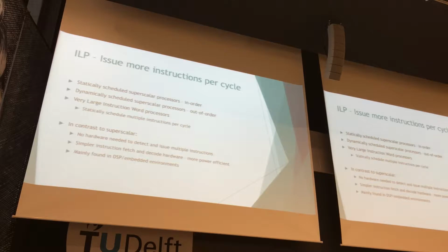Now you basically have, these days, two approaches: a superscalar processor or a VLIW processor. With a VLIW processor, as you already alluded to, it is compiler based, so the way you use these parallel units is via a compiler, which explicitly says at what time what units should be used and how many should be used in parallel. So what is the other one? The other one is superscalar, the one that most of us know. That's for example your RISC processor or whatever.